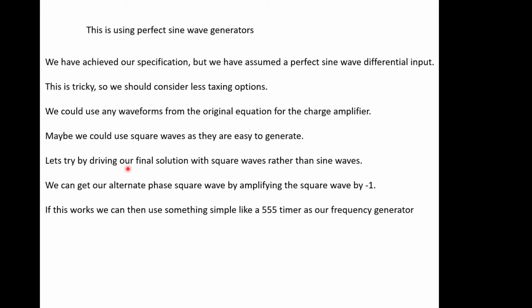Right, now we just have to remember that this is using perfect sine wave generators at the input side. So we have achieved our specification, but we have assumed a perfect sine wave and a perfect differential input with no phase differences, or 180 degrees of phase. And this is actually tricky to achieve, so maybe consider some less taxing options for generating. We could use any waveforms for the original equation for the charge amplifier, as long as they're symmetric, because they just all cancel out and we haven't been constrained by the spec. So perhaps square waves could be used because they're relatively easy to generate. Sine waves are very difficult to generate.